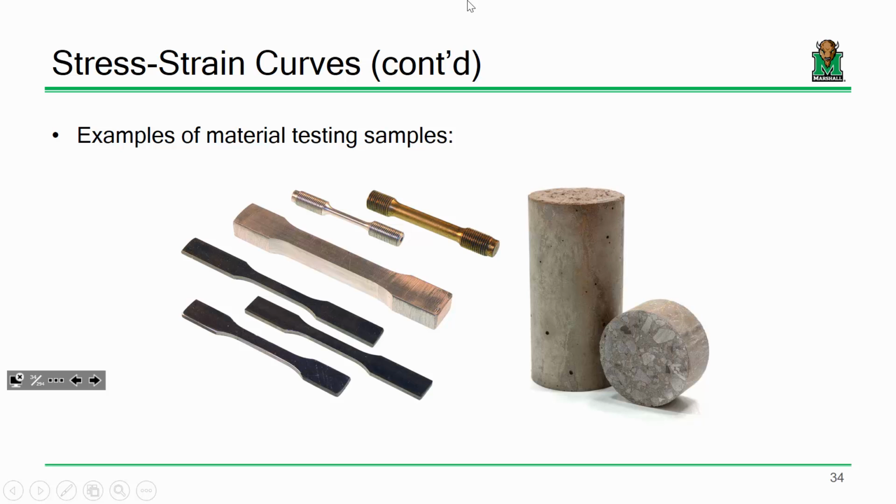Make sense? That's for a specimen in tension. Materials like concrete or cementitious materials like that, they tend to behave better in compression than in tension. The whole point behind the philosophy of reinforced concrete is that concrete is a material that behaves very poorly in tension, so we place reinforcement, like rebar, where the element is experiencing tension. That's the whole point of putting rebar in concrete, to increase its resistance to tension. That's the whole reason why we do that.